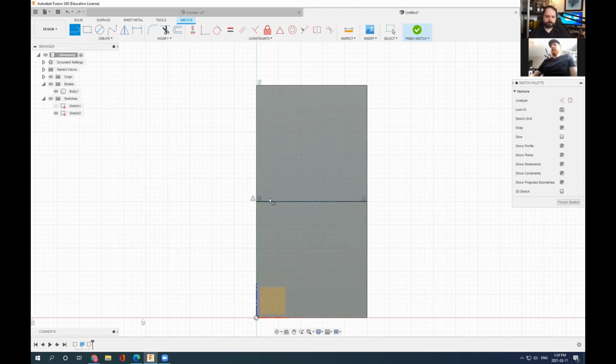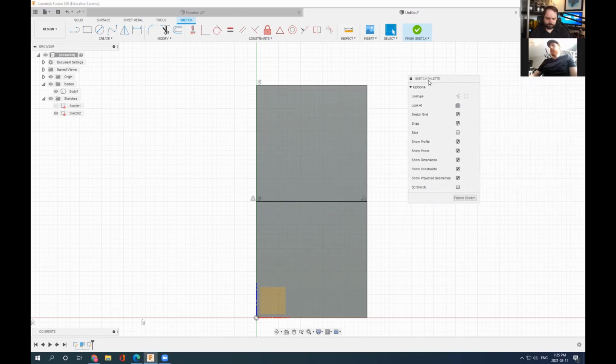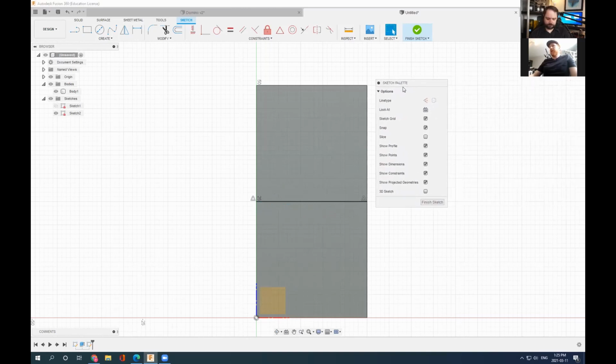There's a way that we can turn that line from a solid line into a reference line for our drawings. And this is really handy when you want to measure something off something else, but not have it be a part of your actual object. So I'm going to hit escape from my line tool so that I'm not in it anymore. And I'm going to look over here on the right-hand side. A lot of things that are happening in the software, when you click on things, you're going to notice that different menus and different options show up on the right-hand side for you. Right now, you should be seeing line type.